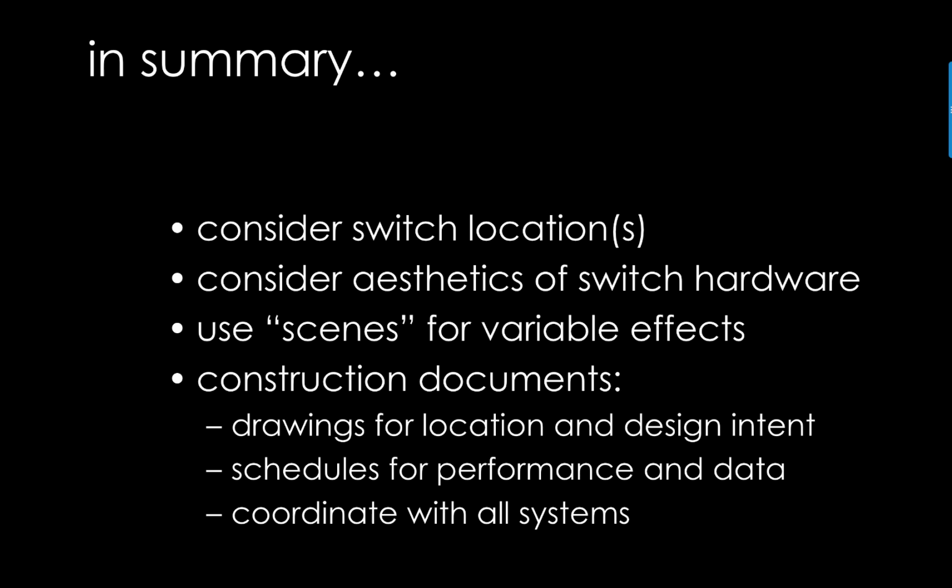And when you do construction documents, this is really the last piece of the puzzle. That's when you take your design intent and start doing detailed drawings that show how all of your light fixtures are arranged dimensionally in a space. And if you have any custom lighting configurations or ceiling construction, that's where you indicate how it's built. You provide all sorts of schedules, which is how people buy out the project, as they usually use your schedules. And make sure that you coordinate with all building systems, including HVAC, plumbing, electrical, and the structure.